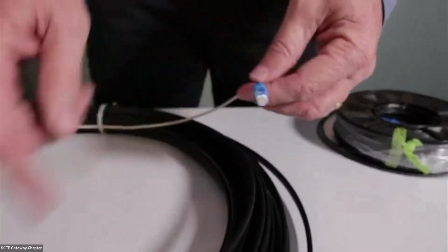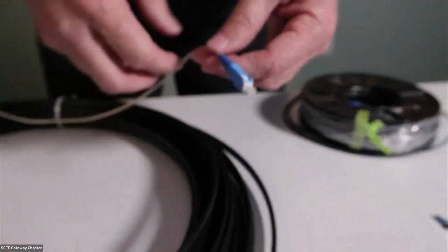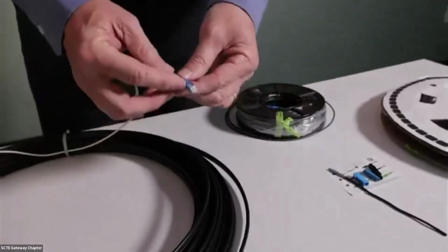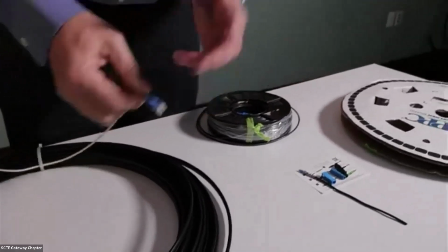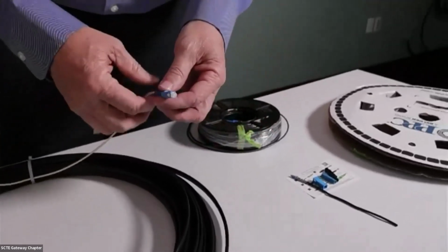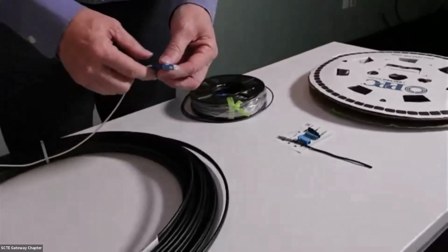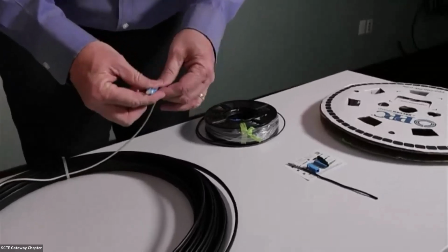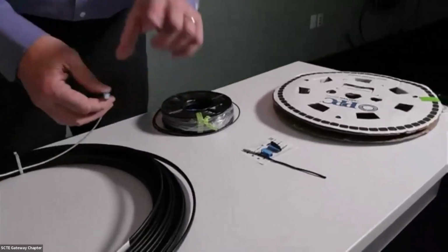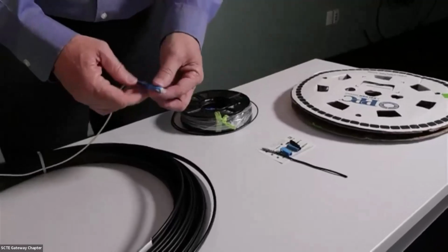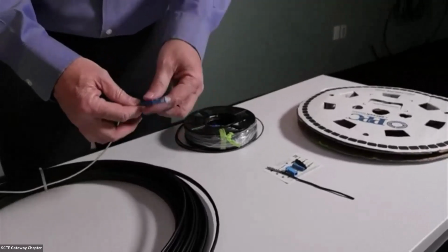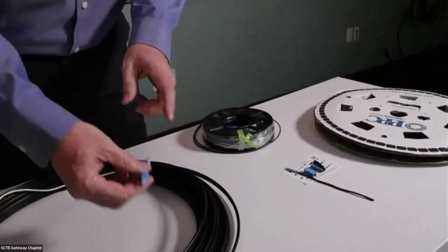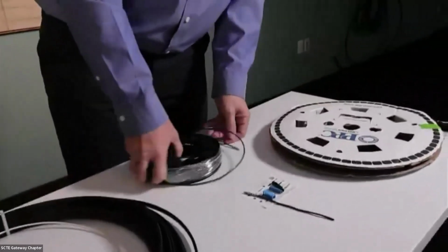There are types of cable where you have the HFOC on one side, and this is just raw fiber. That's the one where you have to put a connector on it. That's where you're going to use a cleaver and other tools to prep it, to put a mechanical connector onto it. We decided not to do that in a live presentation because remember the fiber shards we talked about, we were trying to maintain safety while you're in a classroom environment. So we do have another type of fiber.